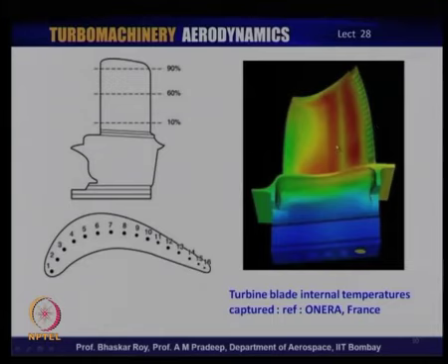So, this aerodynamics actually facilitates the heating of the blades around this area, and this is where you indeed require more cooling, and that is why most of the cooling technology in the early era in the 60s and 70s and indeed in the 80s, the cooling was mostly being done in this area. Okay. But of course, we know, and we will see today, that more and more modern cooling is available near the leading edge as well as near the trailing edge. As the temperature has gone up, you need to indeed cool the entire blade.